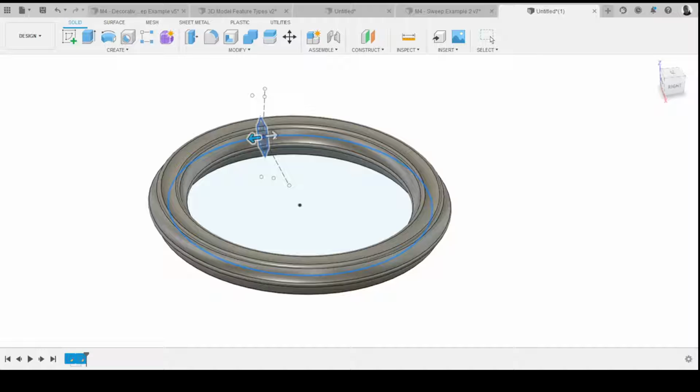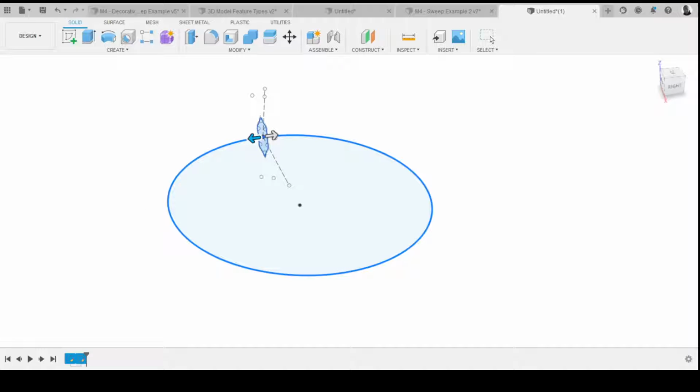What's really fun here with the twist angle, you can play around with the twist angle and get the whole thing twisting around the loop. To do that nicely, I think, if I remember rightly, you have to have a multiple or divisible of 360, otherwise it won't do it. It won't sort of connect nicely at the end. So I just put in a random twist angle of 257 and it's not going to work. So let's try 360.